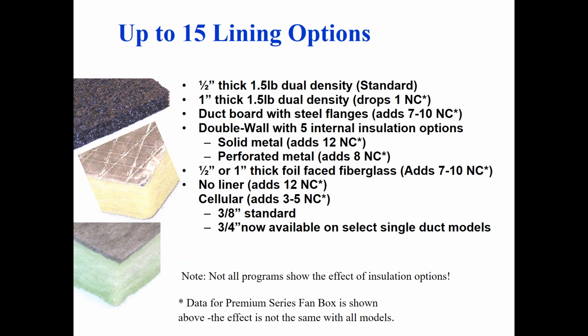It would seem logical to me that you would also be lining the inside of your ductwork on these projects. That's not always the case. Sometimes they put a wrapper on the outside of the duct instead, which is fine, but visually it doesn't look as good, as someone pointed out, for the open ceilings. But you're going to get a 1/2 inch fiberglass liner as standard.